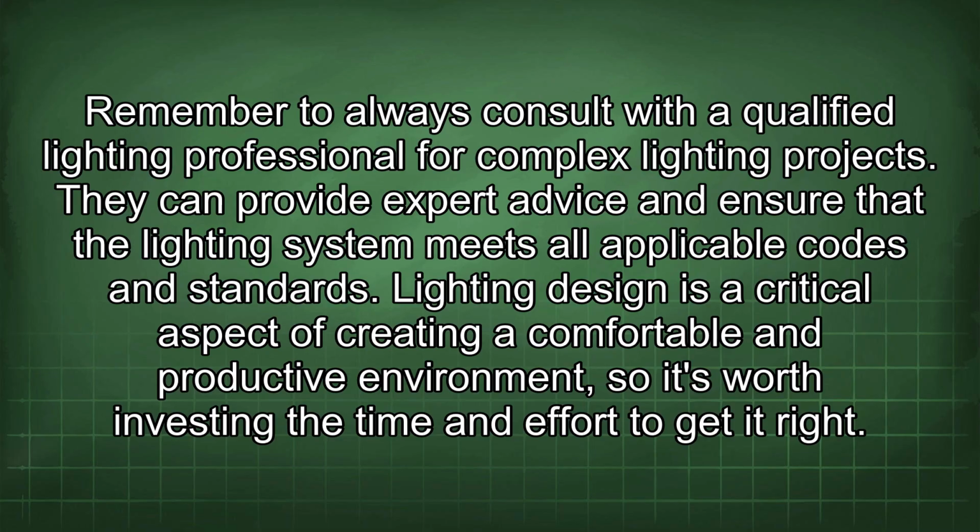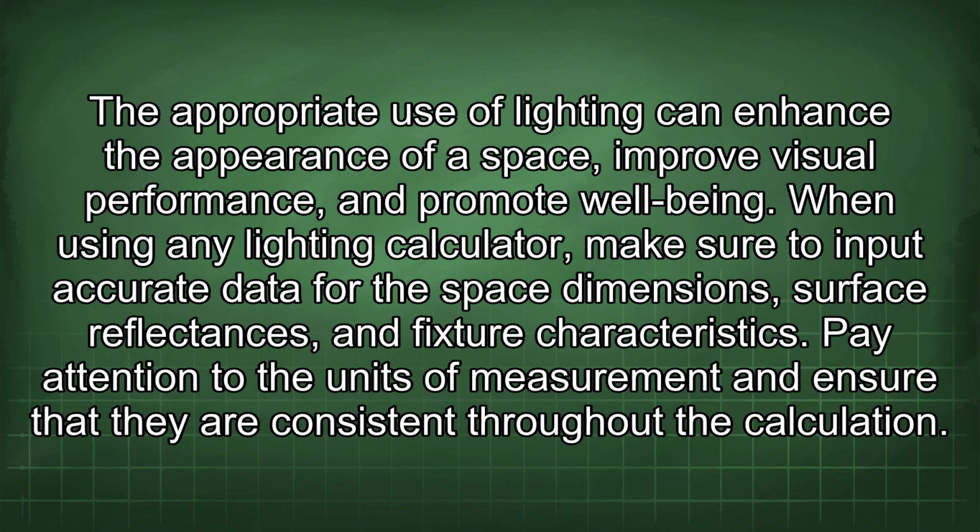Lighting design is a critical aspect of creating a comfortable and productive environment, so it's worth investing the time and effort to get it right. The appropriate use of lighting can enhance the appearance of a space, improve visual performance, and promote well-being. When using any lighting calculator, make sure to input accurate data for the space dimensions, surface reflectances, and fixture characteristics. Pay attention to the units of measurement and ensure that they are consistent throughout the calculation.